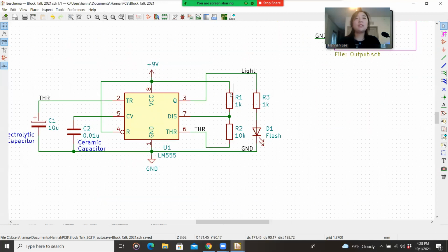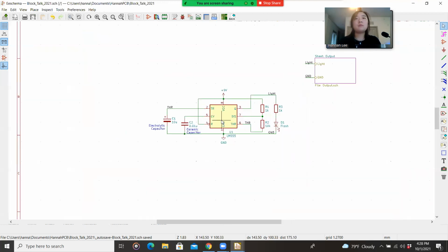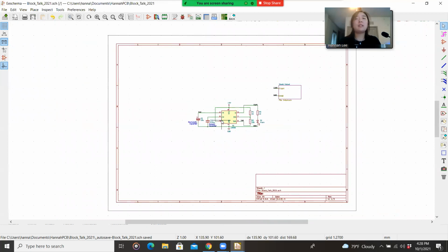And so now notice that instead of having question marks, each resistor has a unique number and each capacitor has a unique number. And so essentially we're naming them when we do an annotation. We're giving them a unique identifier. So that way, whenever we see them eventually on the PCB, we know what that meant. And so now we annotated it.